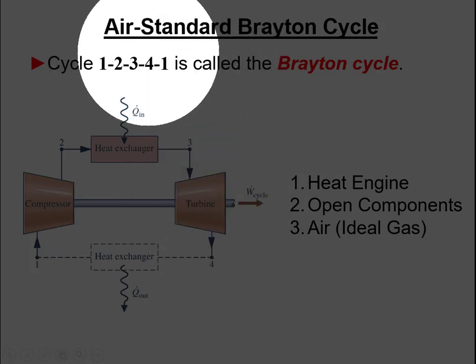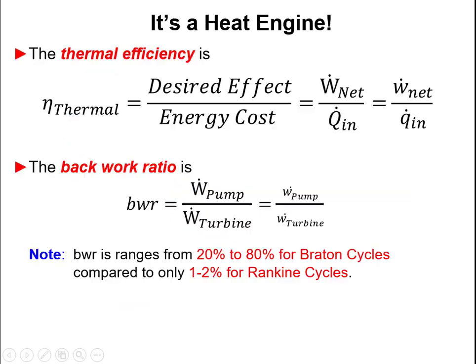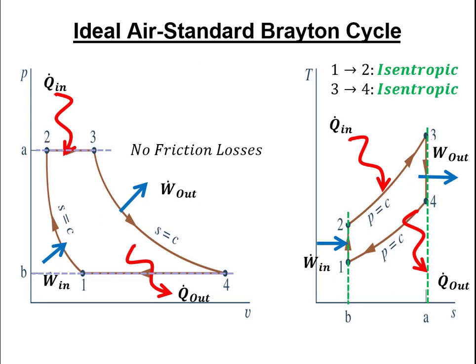Today, we're going to keep looking at air standard Brayton cycles, but we're going to see how we can increase thermal efficiency. For Brayton cycles, we know that when we're adding or removing heat, we tend to assume that the pressure is constant, and at least when we have ideal turbines and pumps, we assume that those processes are isentropic, or that they have constant specific entropy.